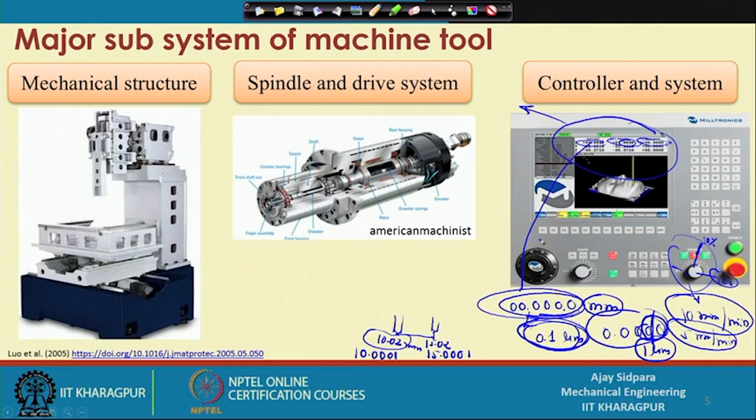And there are some things available, called error compensation. Those things are important, because when you do some type of machining, you have an inherent error inside the machine, that is the expansion of the different parts in x direction, y direction, z direction. So, the machine can sense those types of expansion because of the sensors inbuilt inside the machine structure, and accordingly